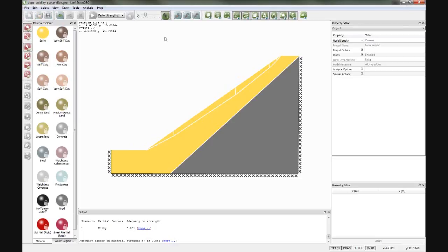Now that's perfectly standard. This is software solving the problem using limit analysis, which is a rigorous plasticity theory. And in plasticity theory, the friction in the soil is modeled using dilation. And so the animation, as this soil slides, is modeling the blocks moving apart, and that's just basically modeling dilation. That gap is basically representing dilation.